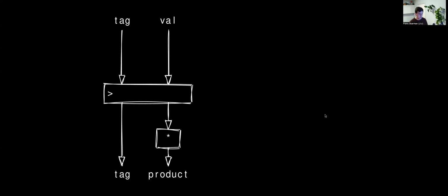As an example, if we have a register that stores an option type, it will have the tag and a value, and that gets stored, and then every clock cycle, this block of hardware, in this case a multiplication, will switch. Even if the tag is invalid, the data that is coming over here will still flip, and so we will consume dynamic power.